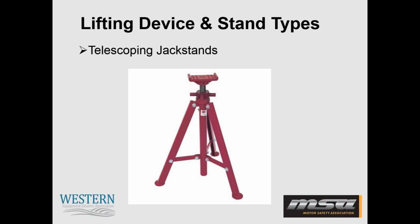There's also the telescoping jack stand, and again these are to be used in pairs, and to use them you remove the pin, lift it to the desired height, replace the pin, and then turn the handle until contact with the item you're trying to hold in place. You want to be sure that you don't use a piece of wood in between this type of jack stand and the load being blocked, as this will point load the wood block and split it. And ensure that you have a good base for the jack stand and that it is properly supported on a firm base.